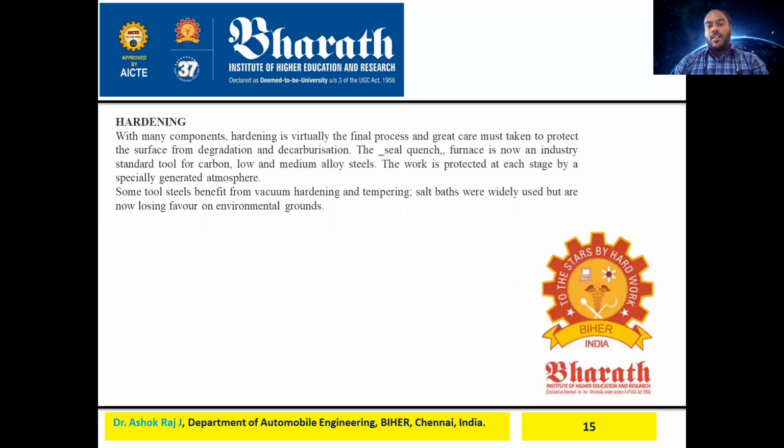And finally, hardening, which many components undergo. Hardening is usually the final process, and great care must be taken to protect the surface from degradation and decarburization. The sealed quench furnace is now industry standard for carbon, low and medium alloy steels. The work is protected at each stage by a specially controlled atmosphere.